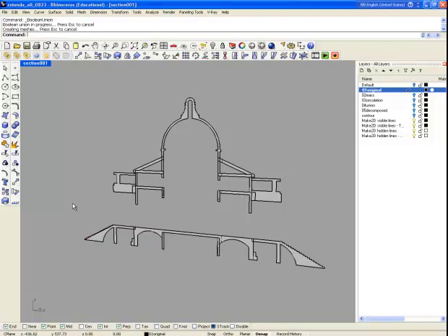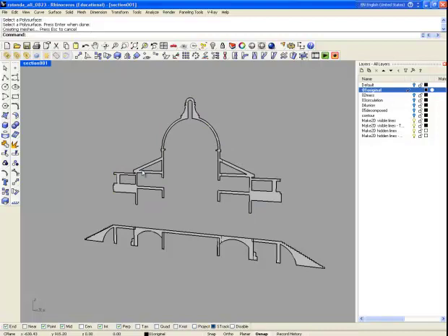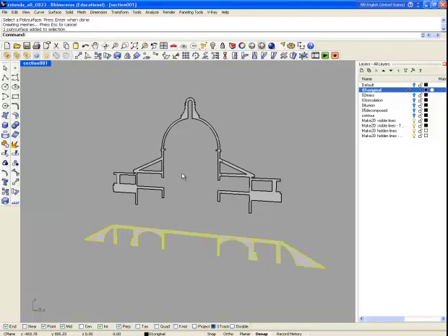Okay, now we are going to use the Merge All Faces command. This command will flatten out, iron out these kinds of overlapped surfaces. So Merge All Faces, select. So this is the one, and then you will see some difference from here to there, right? So now you understand what I mean by flatten out or ironed out, right? And then the second one, this one, and merge all, right? Enter.